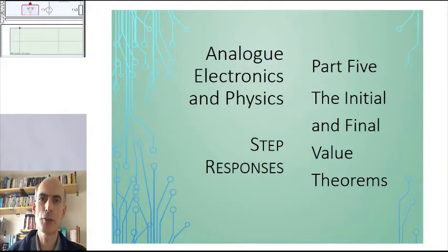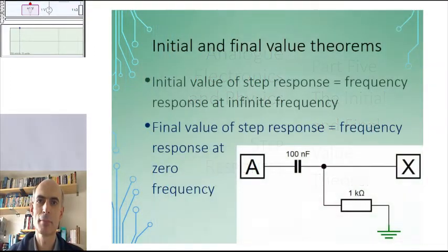This time I want to introduce two very important results known as the initial and final value theorems. So without further ado, these are the theorems. The initial value of the step response, that's the value just after the step has arrived, is equal to the frequency response evaluated at infinite frequency. And the final value of the step response, that's the value after an infinite time when everything has settled down, is equal to the frequency response at zero frequency.